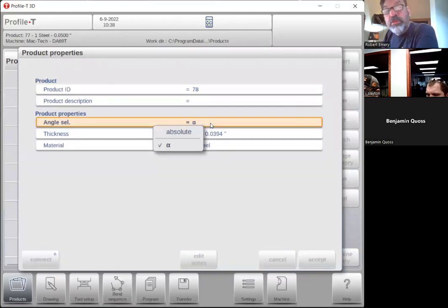Here, we can also change the way we describe the ram position. We can tell it an angle, which is what that symbol there is, or we could just tell it a stroke, a number, with no clue what angle you're going to get out of it. We do a part that's a curling die, and so there's not really a set angle.